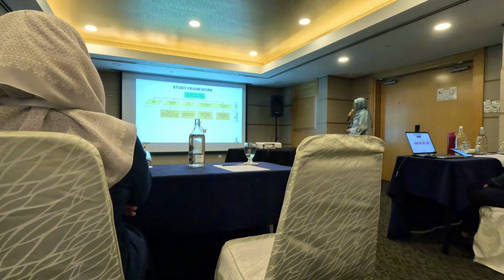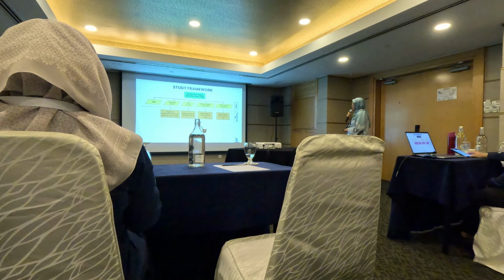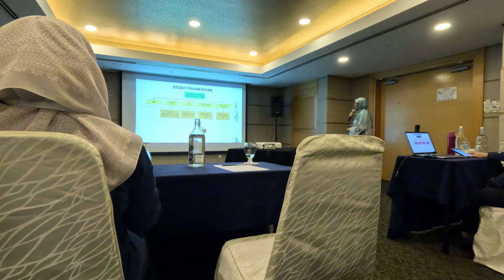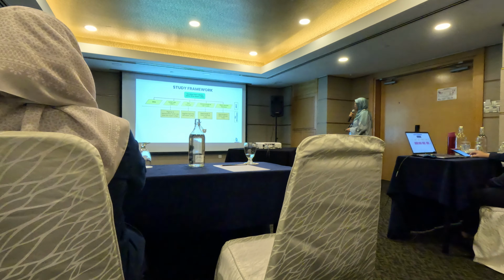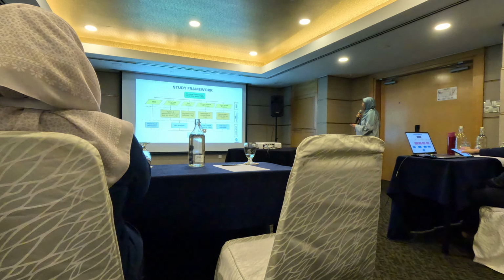The second phase is pre-processing. I need to digitize and classify the land use and soil into GIS layers, and then I need to rearrange the data in SWAT format. The data included are meteorological data, rainfall data, and point source pollution data. The third phase is the model setup. It covers watershed.